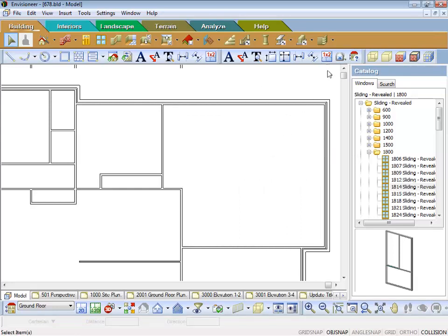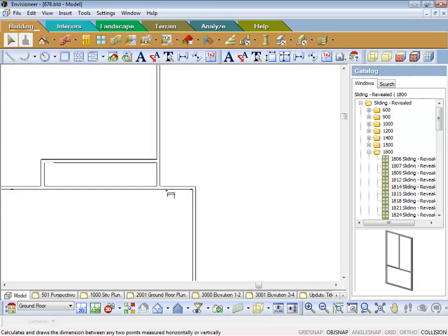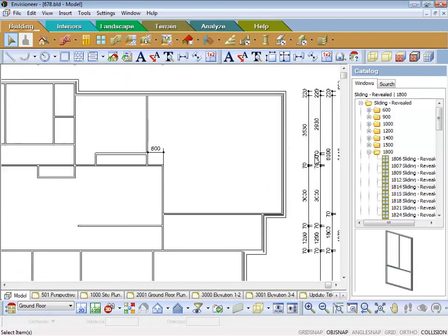Right click finish. I'll just do that again because basically I might want to say, okay, I want a linear dimension from there to there, and pick it there, and I'm happy with that as a linear dimension. An aligned dimension, if I pick the same points, internal corner of the garage to the top, that's what that one does. So that will give you dimensions perpendicular to your side boundaries, or dimensions that will be, you know, over all your slab, just to make sure it's square or anything like that, but that will do it on the angle.